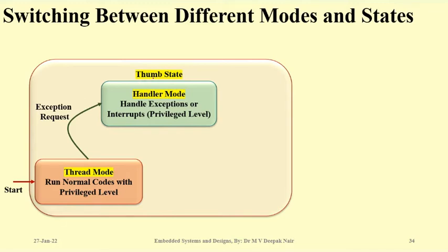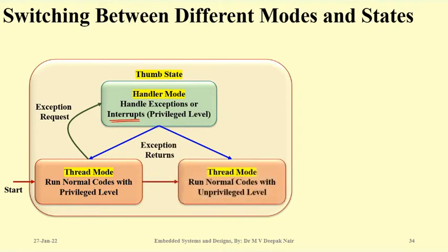So right now you are in handler state. That means you are still running in a normal mode, but handling an interrupt. After that, from here you can come back to the thread mode. That means once you have completed the interrupt, you can come to the normal program. Or it might be possible you may jump to thread mode with unprivileged level. That means you will not have complete access to your registers and other resources.